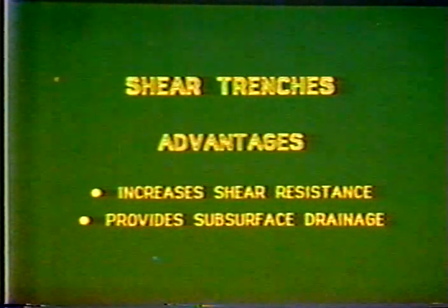That's just another shot of the toe. You can sort of see a hump in the toe there where apparently the failure plane or the toe is humping up. It's failing. Just a shot of the surface there shows the crack in it, and it's dropped down somewhat. So this slide was corrected, and the reason I want to show this is another technique that you can correct a landslide, and it doesn't matter whether it's a big slide or a small slide. The technique's the same. This is a shear trench. This slide was corrected using a shear trench, and let's look at the principles there.